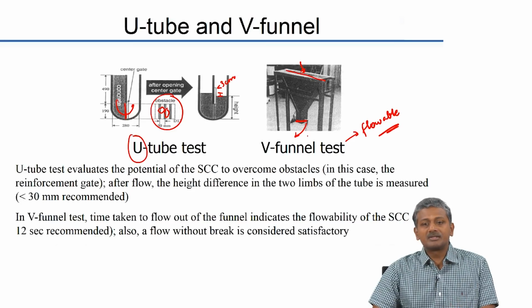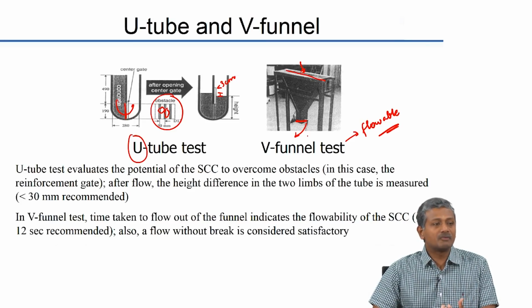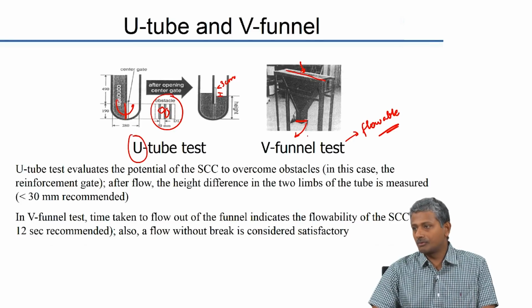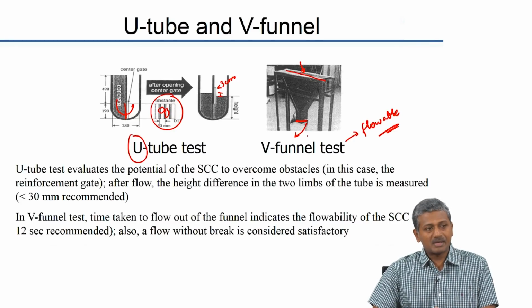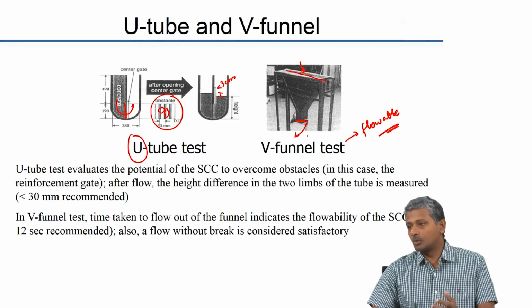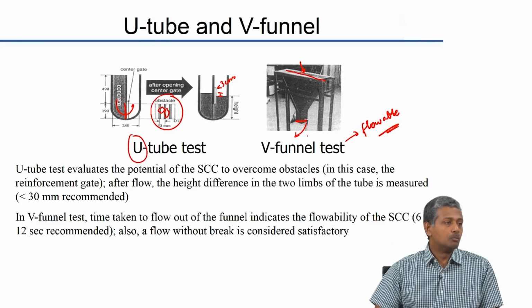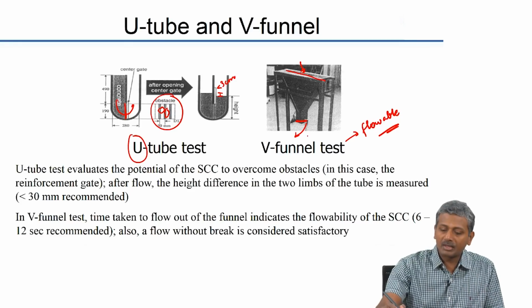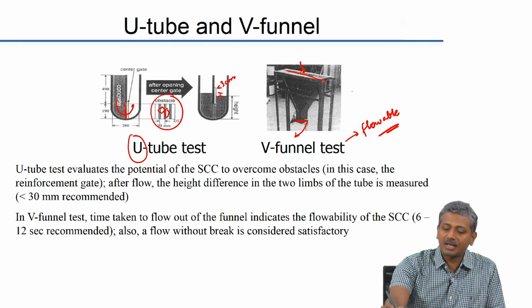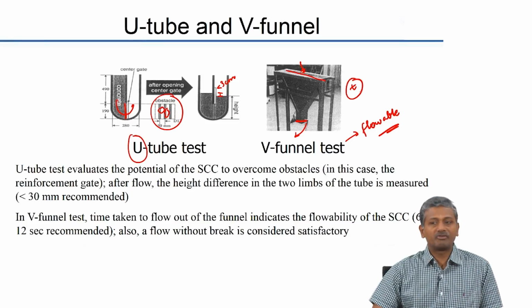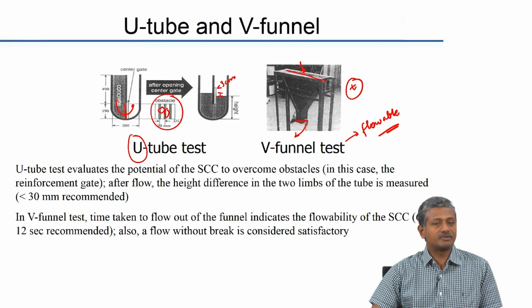Okay. If you imagine it is going to be a very cohesive or very stiff concrete, it will not fall at all, right, it will not fall out of this opening at all. If it is semi-stiff concrete, it may fall out but start coming down in chunks, it will not really come down as a single pour. For self-compactability, you want it to come down typically as a single pour. And generally what there are specifications about is the time it takes for the entire concrete to get emptied from a V-funnel. You can also do this test in a different way.